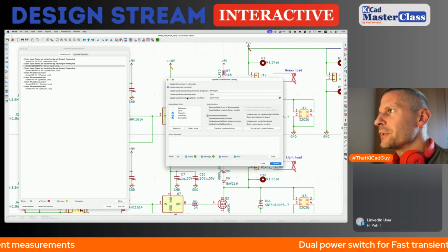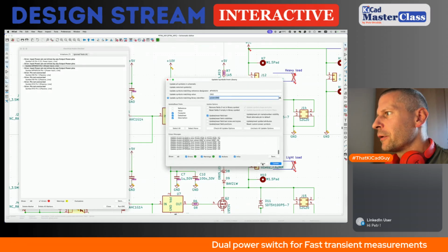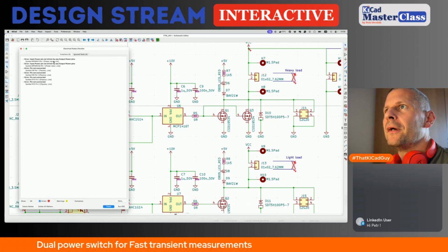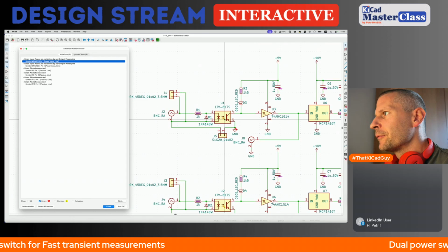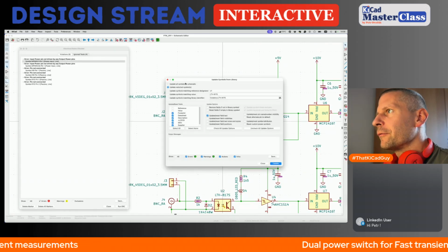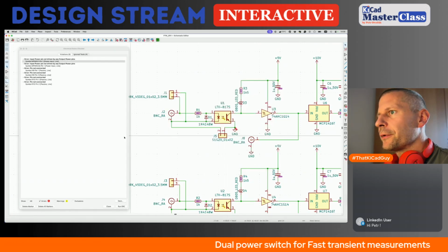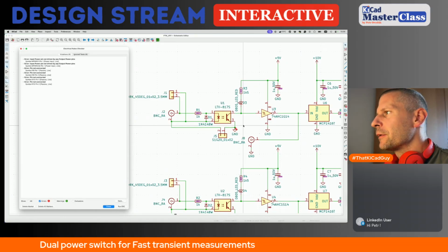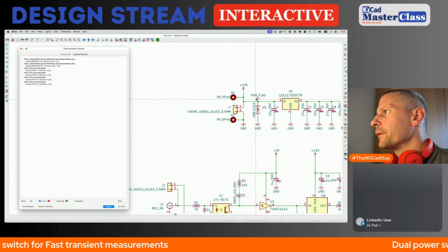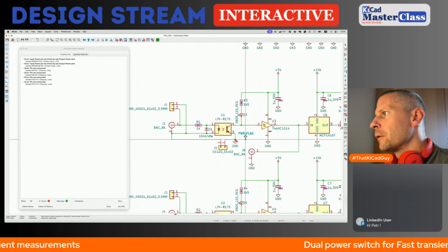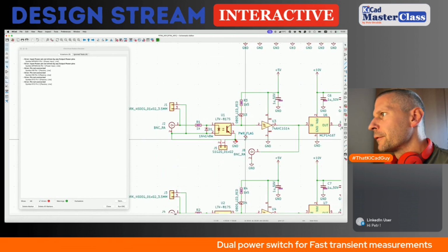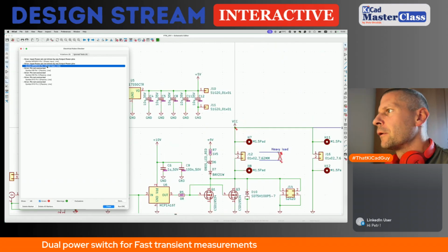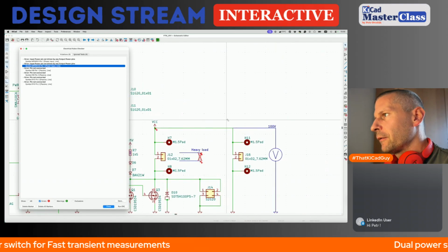We have 2 possibilities: to update all the symbols or change them. So let's see if it helps. Yeah, it helped. So, you know what, I will update all symbols to avoid these stupid mistakes or findings. So here is a power flag for ground, VCC as well.